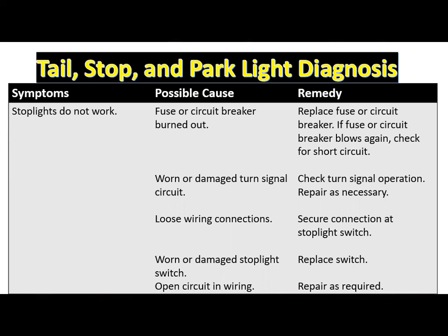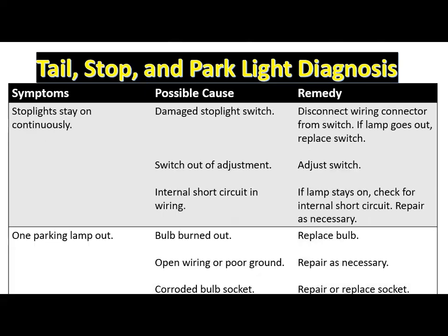Worn or damaged turn signal circuit: check turn signal operation, repairs necessary. Loose wiring connections: okay, you have to find that out. Secure connection at stoplight switch. Worn or damaged stoplight switch, open circuit in wiring: replace switch or repair as required.